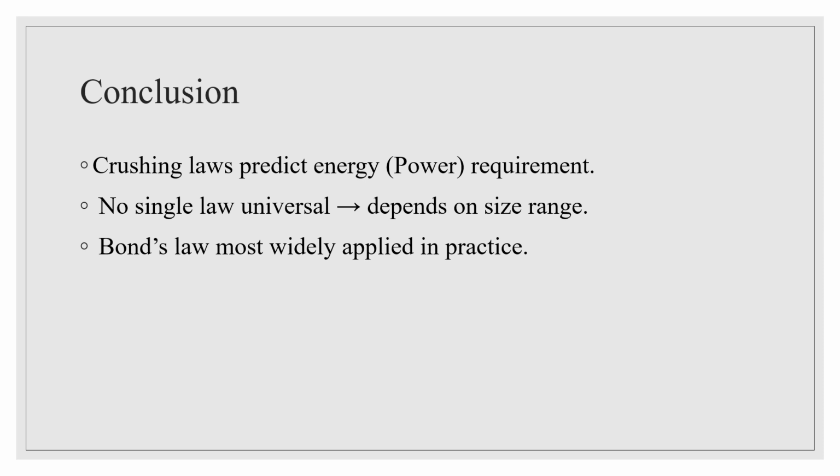The conclusion of this session is that crushing laws predict energy or power requirement. No single law is universal; it depends on the size range, and Bond's law is most widely applied in practice. So this is the theoretical part of crushing laws. In the next lecture, we will discuss in detail how to calculate power requirement using Rittinger's law.